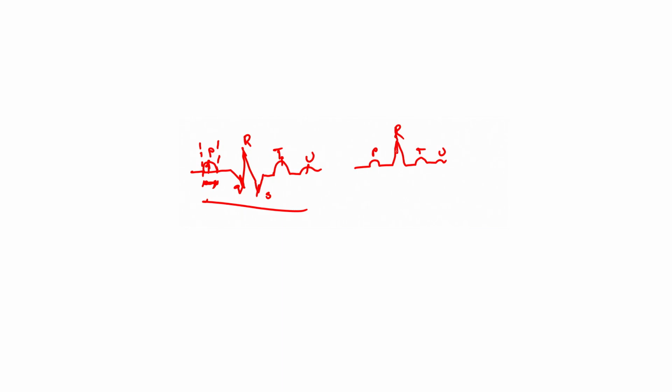If I want to calculate only the peak of R, I have to understand how to differentiate between a peak and a point. When I do the digitization of the signal, we can take different samples at different intervals, right, but how do you decide this particular value is a peak? In order to do that, I have to compare the peak value with the next subsequent value